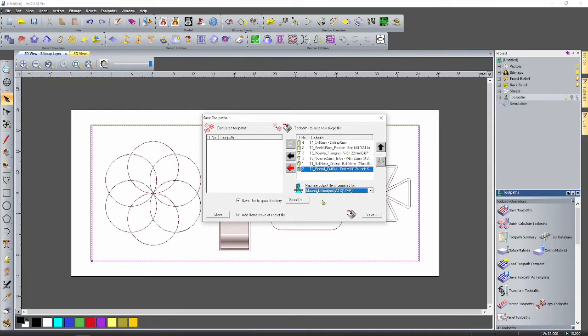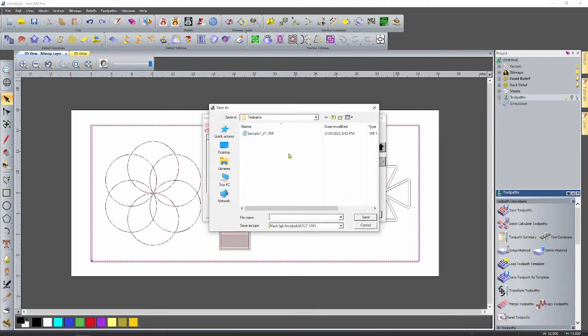If you open up this menu, it's a huge list of different controllers like Siemens, Fanuc, Fagor. The controller on our CNC is a Mach III ATC, and it's inches. So I'm going to use this, and then save. And let's overwrite this. Should be fine.